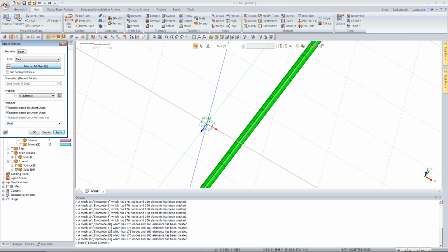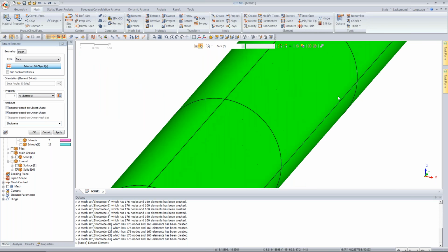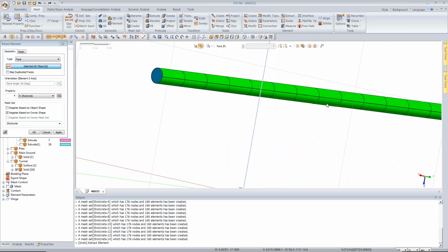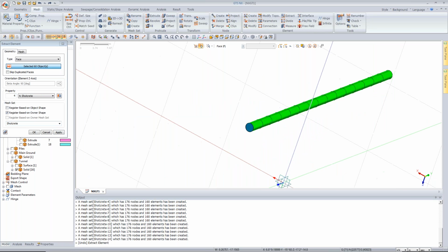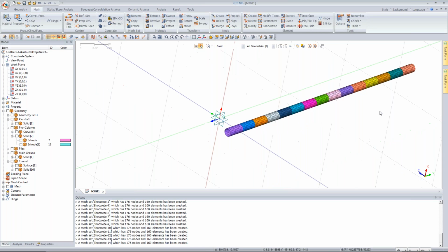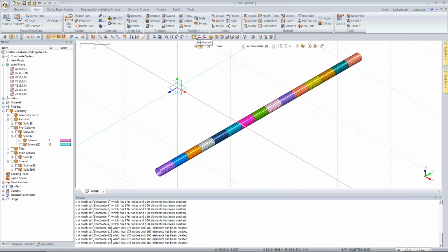I'm giving it the name shotcrete. Going to the unselect mode. Maybe while intersecting, I intersected one of the outside faces. So just to check, you can rotate it. Looks good to me now. Fine. Now just say OK. Still, to make sure, I can see the complete shotcrete now. Fine. So this is how you create it.